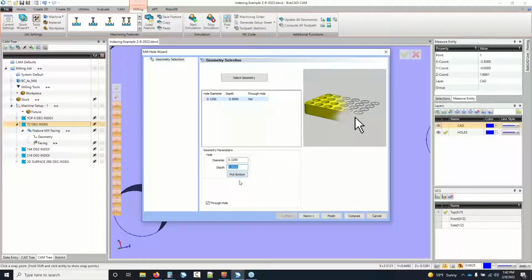And so we'll see it actually is just a 1/2 inch deep. Now, right here's a little button, and if you forget to check it at this point, it's not a big deal. It's on the next page as well. But there are 2 types of holes you're going to drill. They're either through holes, meaning they cut all the way through, or blind holes, meaning they don't cut all the way through. So if I uncheck through hole, it means I'm using a blind hole, which is what these are. The difference between the two is that if through hole is checked, whatever your depth is, we're going to add 50 thousandths onto it. So in my case, I want a full diameter cut, a 1/2 inch deep, and I don't want it to add any extra. The only extra I want added is the tip. So we'll go next.